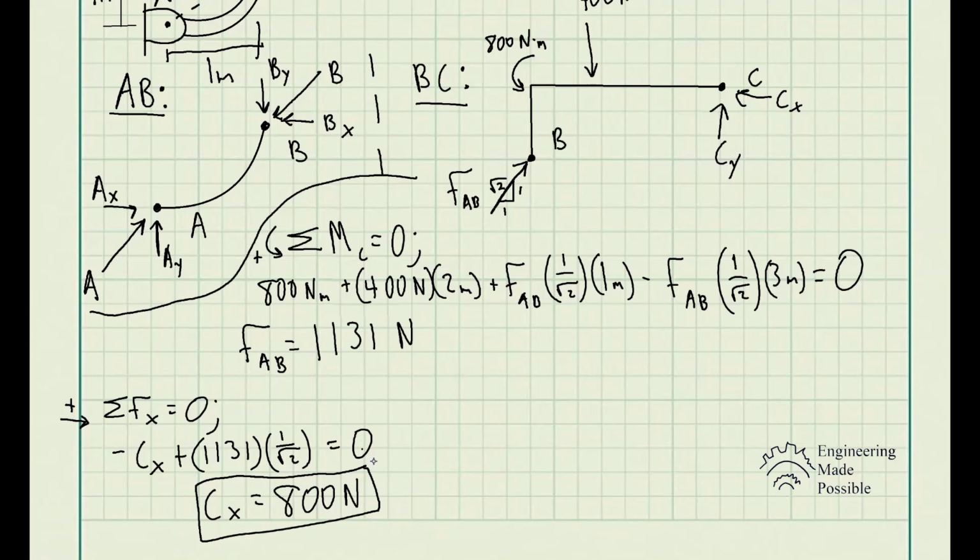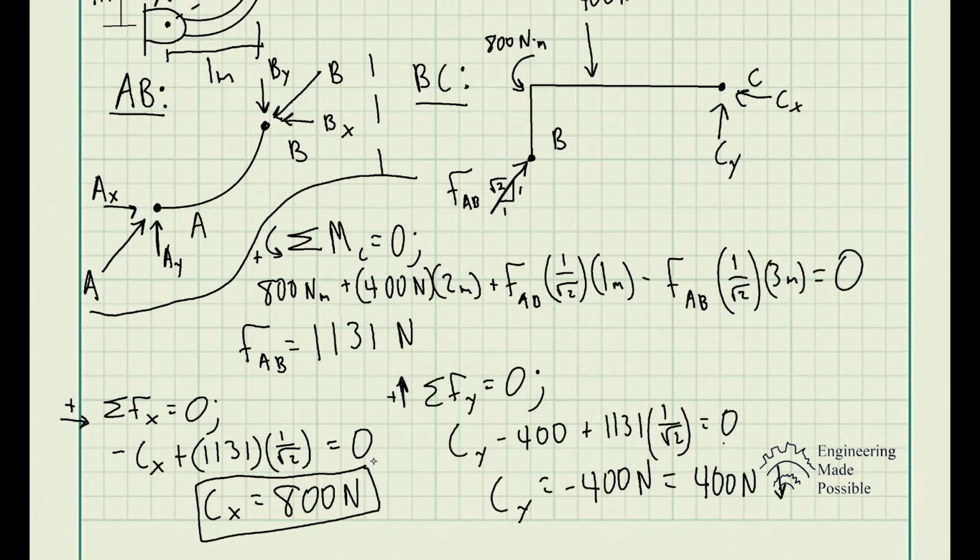Our assumption was incorrect. Now you could double check the slope, the angle of this force. You could do the sum of moments with respect to point A for this specific member, and you'll see that Bx is equal to By, so there's a 1-to-1 ratio, which basically gives you the same angle here. And so this is how you solve problems dealing with frames. You could solve for the reactionary forces with the entire structure, but sometimes it may be simpler just to split up the structure into its respective members and solve accordingly.